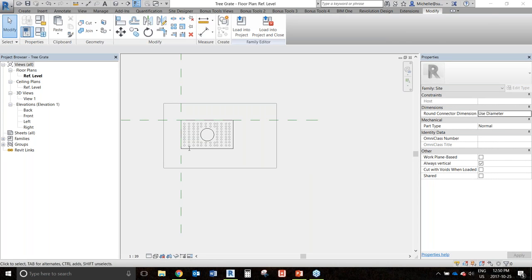Do you build all your own families, or do you download some? If so, where do you download from? Honestly, it's been a really long time since I have downloaded families from online, but it's still necessary for some clients. I know that Bradley, as an example, has a lot of content for Revit that a lot of people want to get their washroom accessories from if they really need that level of detail. But honestly, for most of the big things that I'm using 90% of the time, I'm going through and customizing myself, just for the fact that you do need to think about your deliverable. And usually stuff online can be a good starting point, but you always have to go through and clean stuff out.